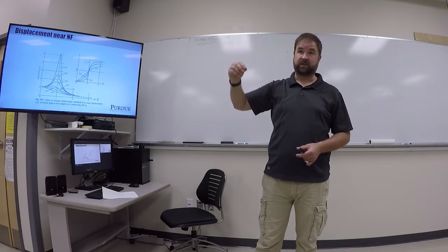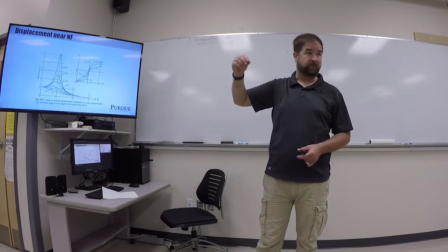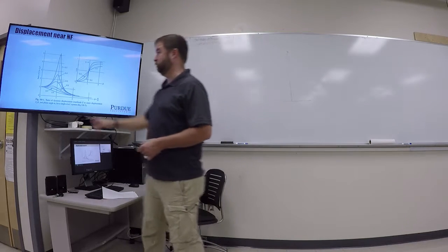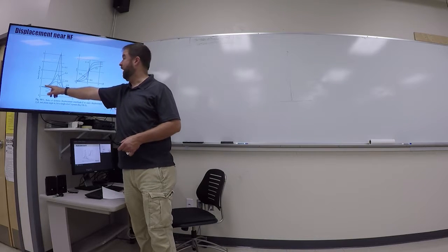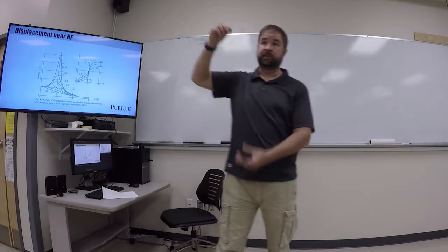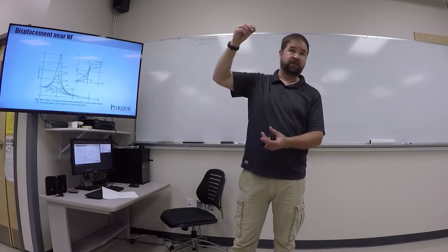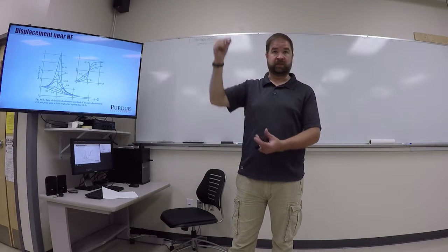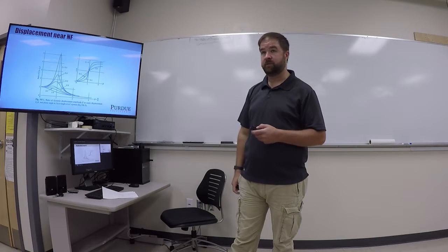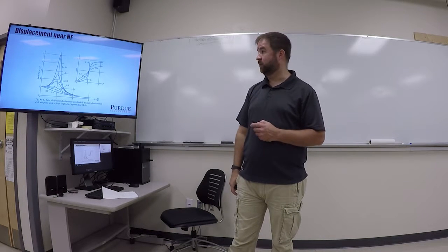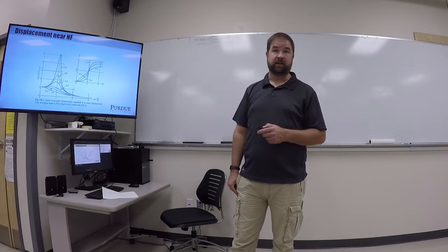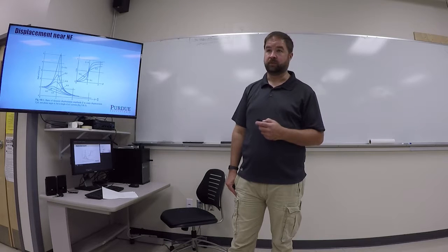So my input is equal to 1, and my output, the movement of the mass, would be 1. So at very low speeds, it's 1 to 1. As I approach the natural frequency, I will get extremely large displacements. And then once I pass the natural frequency, that will get smaller and smaller. That's what this chart is showing us. Okay, so again, reinforcing the idea, with little damping we do not want to be operating at a natural frequency because we'll get extremely large displacements.